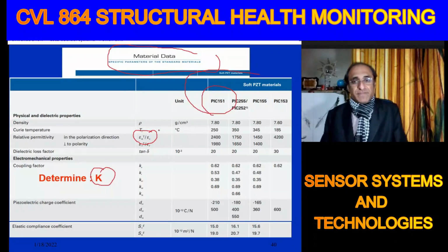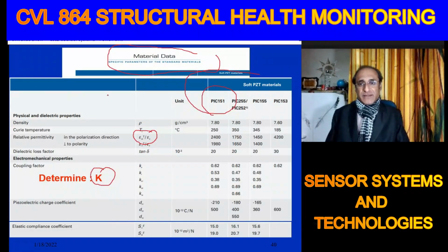See, it has to do with the parallel plate capacitors. In the case of the parallel plate capacitors, Q is given by C into V, and we can input here the expression for C. It is the permittivity into the area, divided by the thickness, or H, multiplied by the voltage V. This is how electric permittivity comes into the picture.